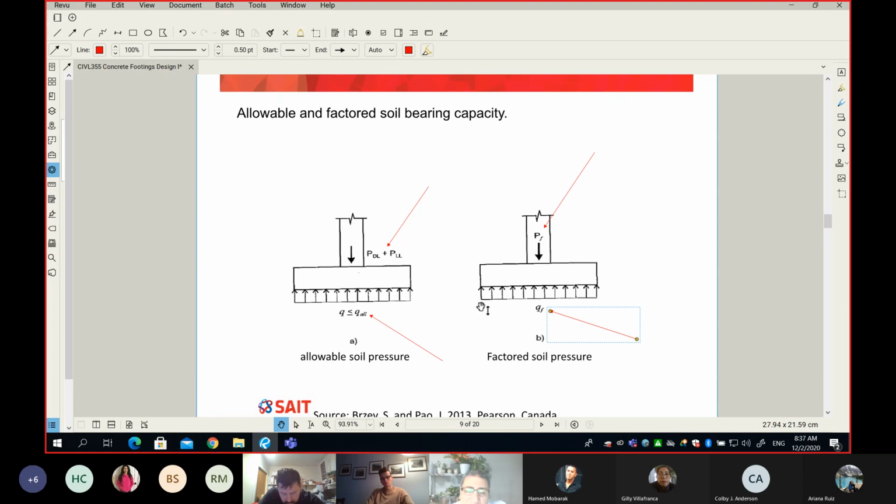The thing is, the geotechnical design did not pick up as fast as the structural design. Structural design, very quickly, changed from working stress method to ultimate limit state method. But geotechnical design, some of the old engineers still until now, probably give us in the report something called Q allowable, not the Q factor, okay?